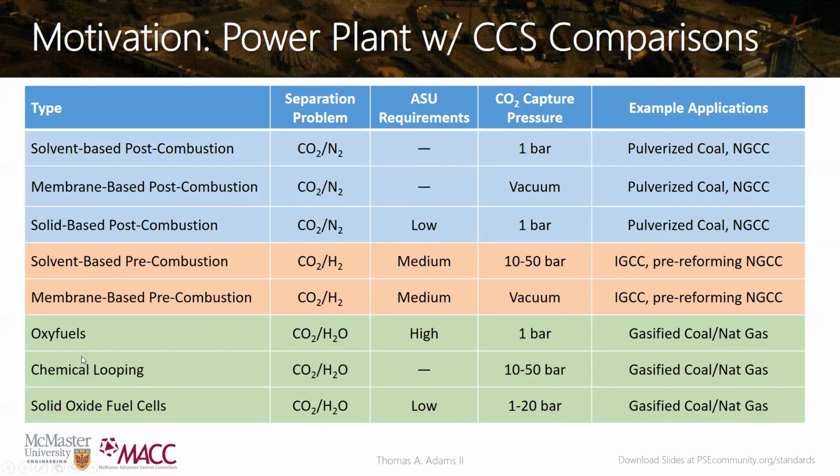So the idea is that this is a very different idea with solid carriers, and then we have solid oxide fuel cells, and these use basically electrolytic, electrochemical processes where you have oxygen nitrogen separation happening at the same time as your fuel oxidation. So oxygen moves from the cathode into an anode, and then that's where the fuel is oxidized. So nitrogen never gets into your fuel. And all of these have a CO2 water separation downstream.